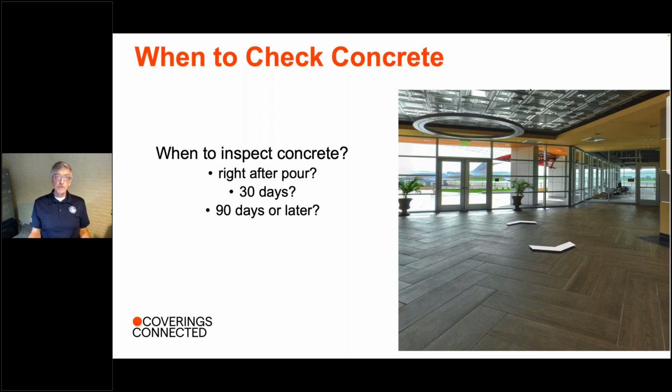Well, in the case of a new construction job, like this picture that we're looking at here, which happens to be an airport, the tile contractor might not come onto the job for a number of months or weeks or a very long time. And in this case, that concrete is going through a curing process. So the time between when the concrete contractor checked it for flatness a couple of days after it was poured, and said, yep, looks good, we're out of here, and the time the tile contractor comes onto the job, something might have happened with that concrete.